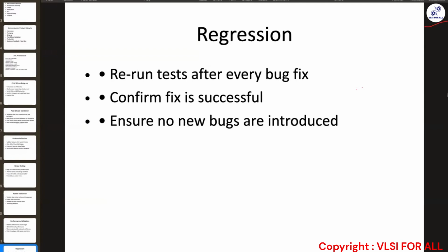And then you try to write all the configuration details of that particular motherboard, basically with the silicon stepping you have used. When I say silicon stepping, just like drivers, you will know there will be driver versions for all the drivers we use, right? For every domain you will have a driver version. Just like that, even for silicons there will be stepping.